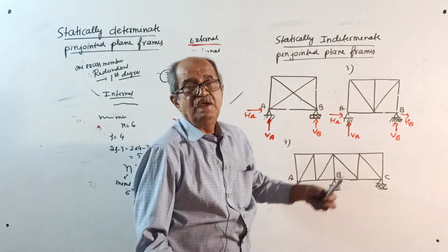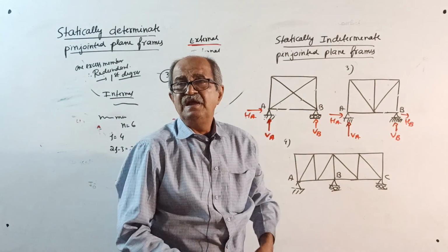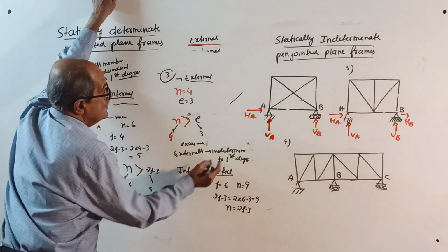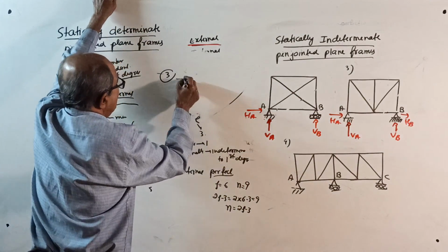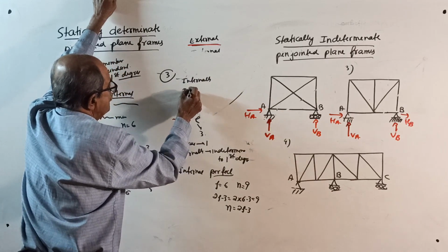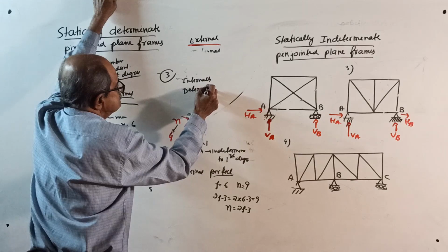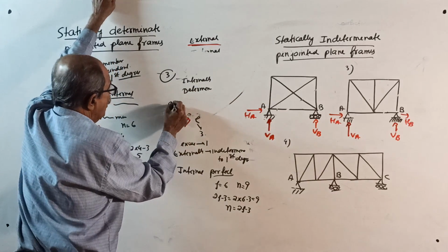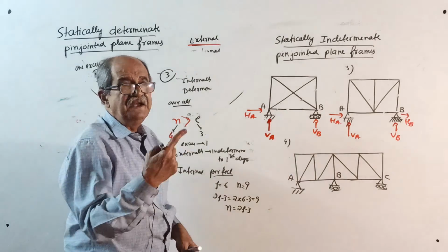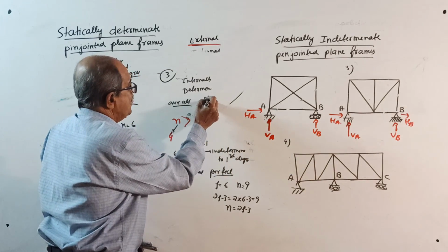Therefore, internally it is determinate. Therefore, frame number 3 is internally determinate. Therefore, overall, it is statically indeterminate to first degree.